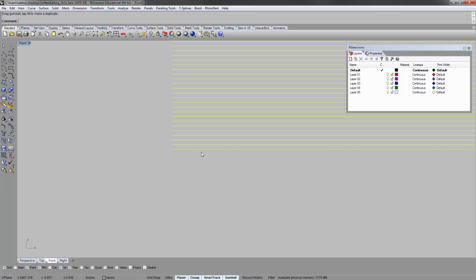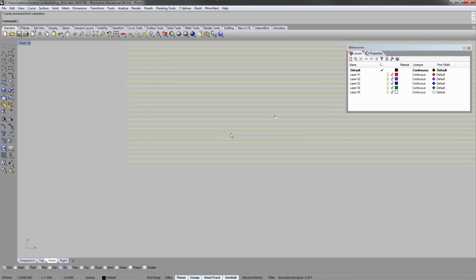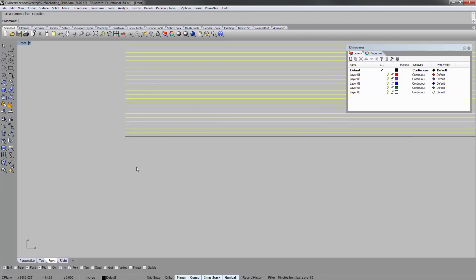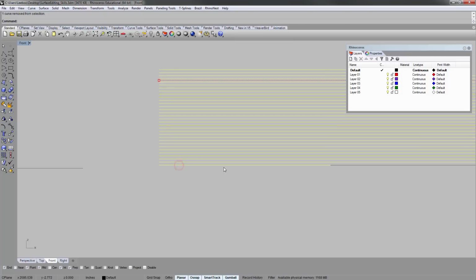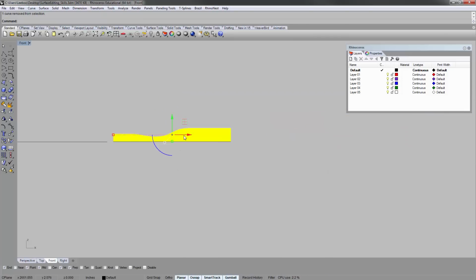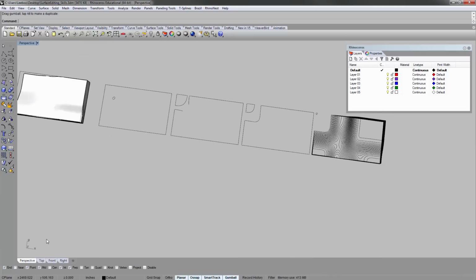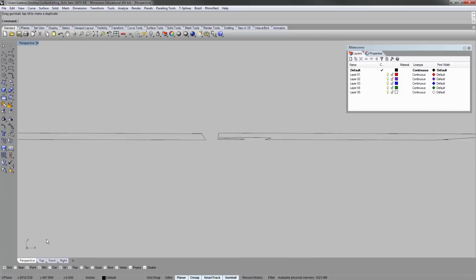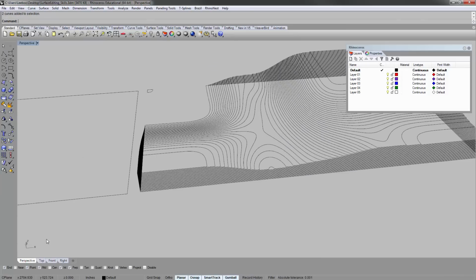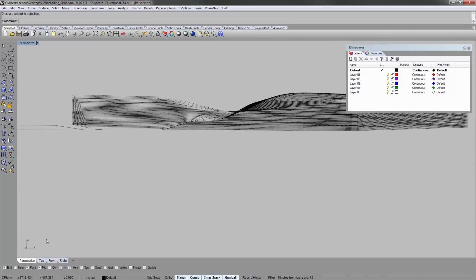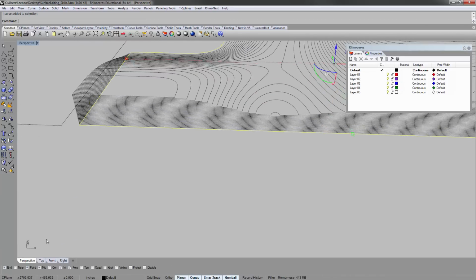I select everything together and I go to the next layer, and by holding down the control key, I can deselect the last layer, pull it out, then deselect the last layer. Sometimes you'll have multiple, but that basically allows you to spread it out. If I go back to the percent, I just have to be careful because sometimes you'll have stuff on the same contour layers, so you might have more than one patch of things on the same Z height, but basically you can spread it.